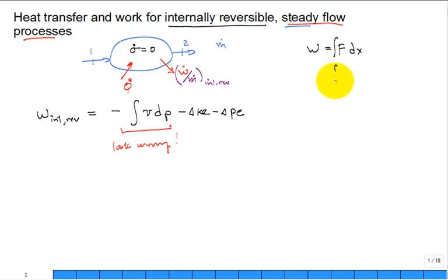And that's equal to the integral P dv, the boundary work. So when I look at this, it just looks wrong, doesn't it? Is there a typo, Professor? Should this be the integral P dv? Nope, that's a surprising result. It's the integral v dP, just the opposite.